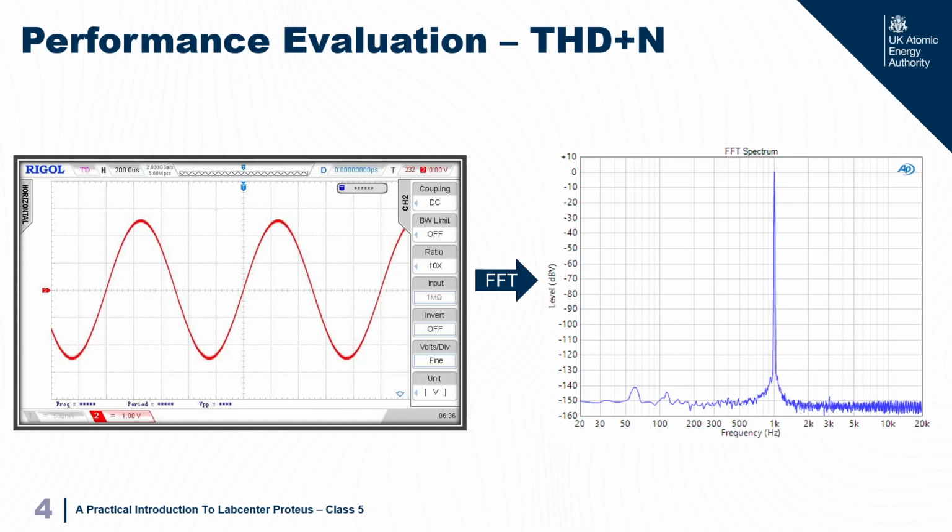But just an example, 10 dBV is 10 dB voltage. That would equate to about 3.16 volts. Okay, so at the top, 10 dBV is about 3.16 volts per graticule. At the bottom, we've got minus 160 dBV, that equates to 10 nanovolts. So on the same scale, you can see the difference between 5 to 10 volts at the top, and taking up the same amount of distance at the bottom, you're at the nanovolt scale.